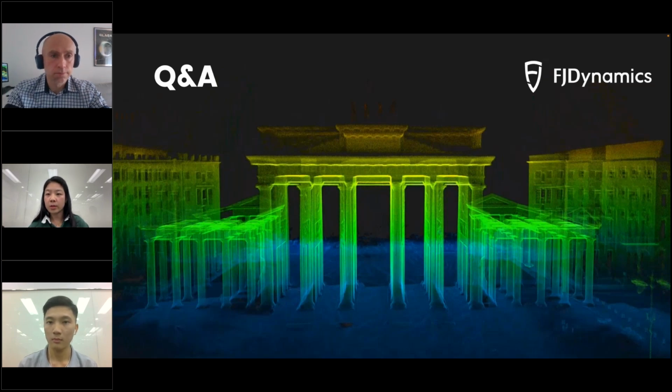Great. And then we have another question. Will static scans and slow movements of the SLAM system increase the accuracy of the scanner? In my opinion, yes. Are there any tips and tricks that people should keep in mind when doing this? Well, smooth movement, stopping for a while very often.